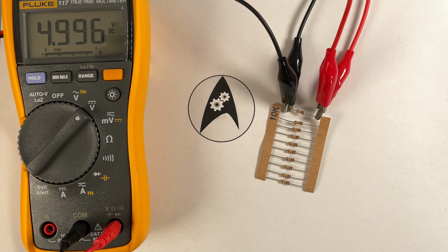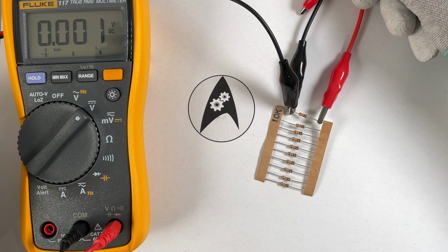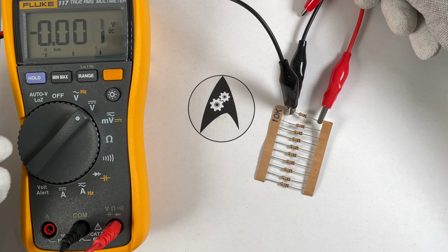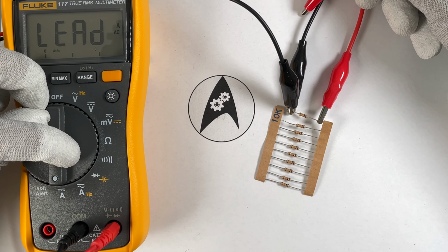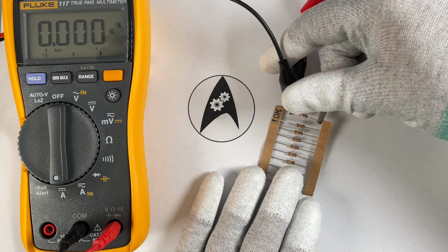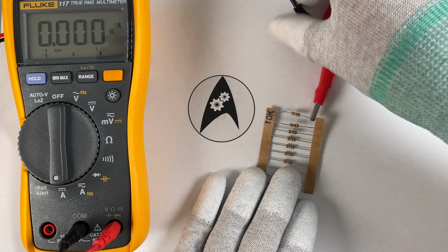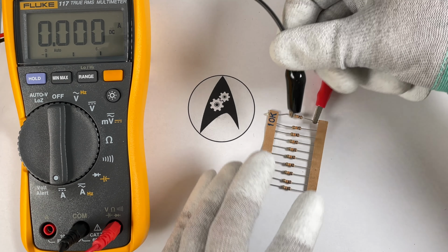And in order to observe Ohm's law, let's now measure the current flow through the resistor. And before we do so, let's switch off the power source. And now reconnect these measuring tips. And in order to measure the current flow, we need to integrate the multimeter into the circuit. And before we do it, we set it to measuring amps. And what we also need to do is connect the amp meter directly to the resistor. This is the connection leading to the amp meter.